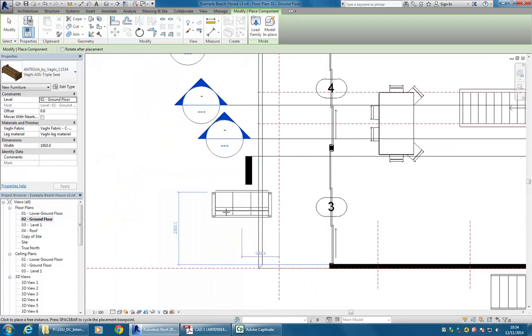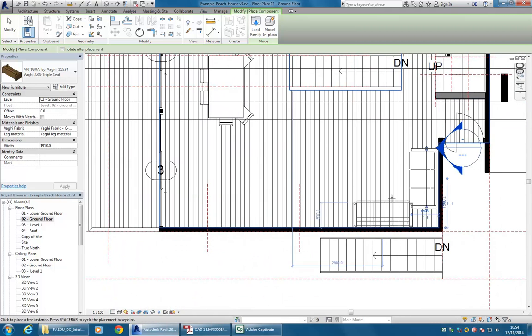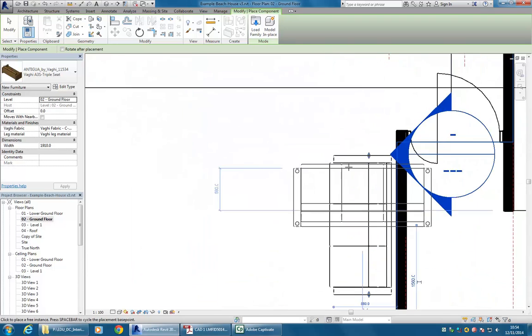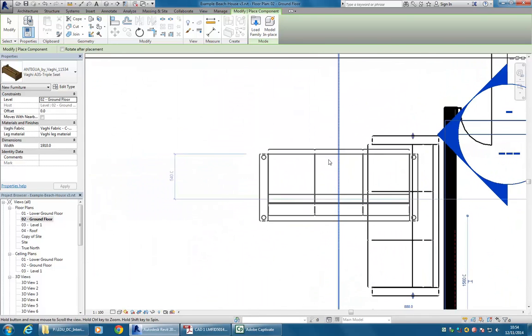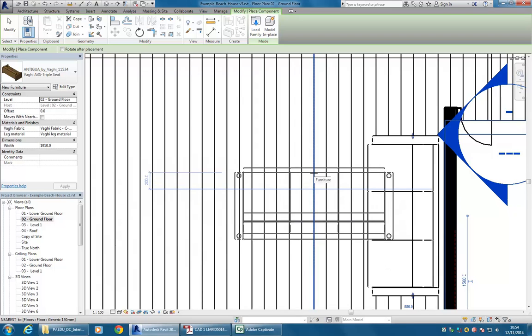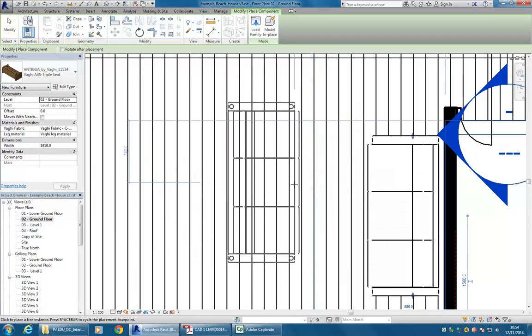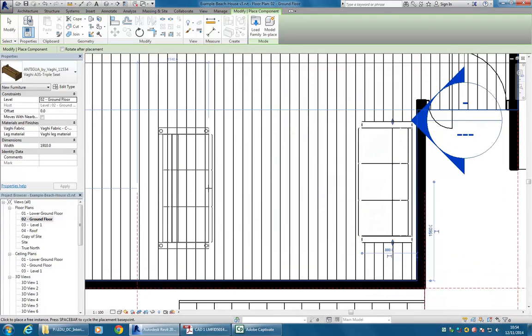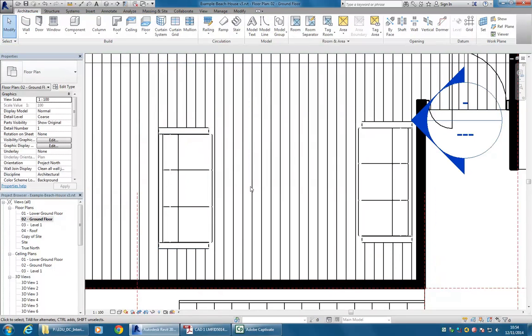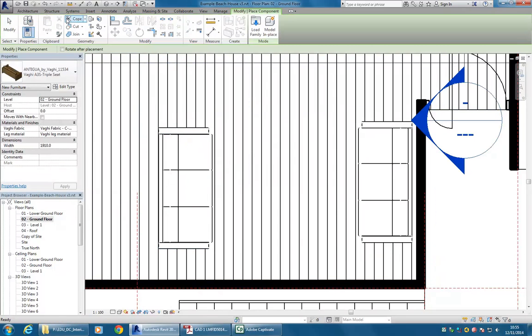It's not picking that chair up, unfortunately, but anyhow, you might see that happen maybe if I go near this. No, they're all straight, but essentially it's highlighting those floorboard lines there, and you can see the lounge is rotating to go in line with them. And so just watch out for that when you're using space to rotate things. It can rotate at angles that you won't expect.